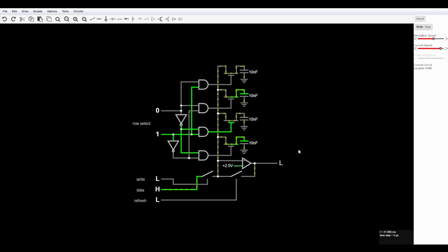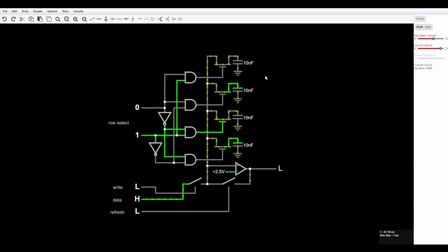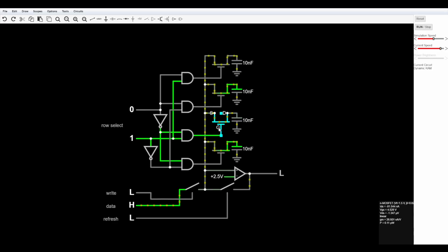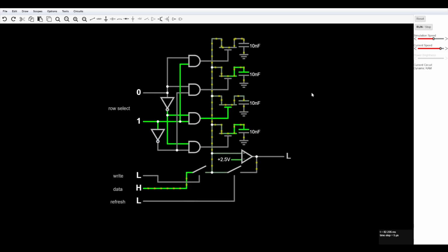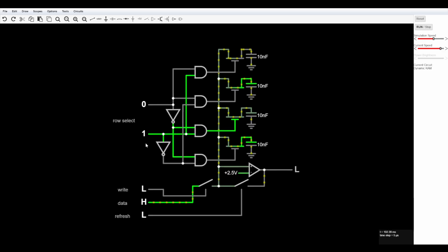All right, now we're coming into dynamic RAM. In this case, we have 4 bits. And you'll notice each one has a capacitor, each one has a transistor. So simpler, but you have to refresh. Now this is a simulator, so there's no idea of us losing data here. But we start with, let's see, which one? Okay, so 0, 0, and then I'm guessing that's 0, 1. All right, so we're looking at the very bottom one. I mean, we can refresh.